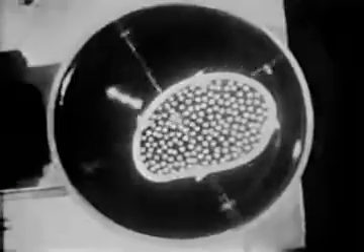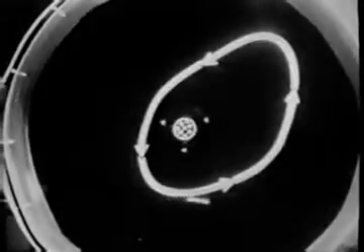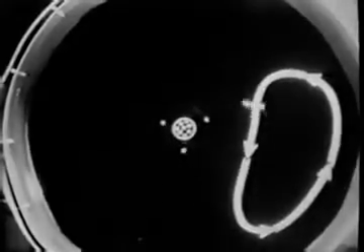In the spiral vortex tank, the flow is non-vortical, except for the concentrated vortex core, which accounts, so to speak, for the whole motion. All fluid circuits surrounding the core have the same circulation, because they contain the entire vorticity flux. All fluid circuits not surrounding the core have zero circulation because they contain no vorticity flux.